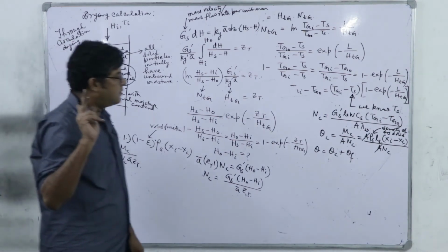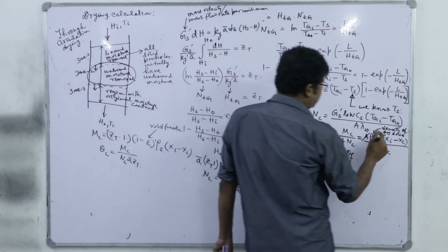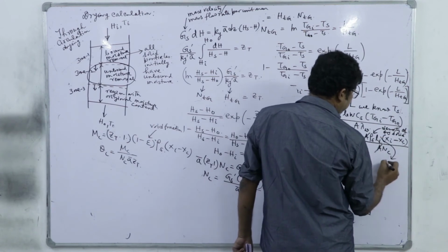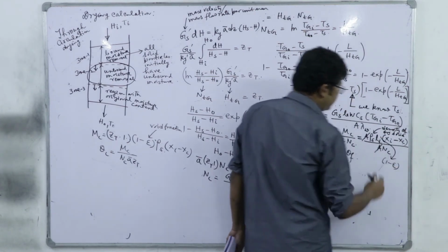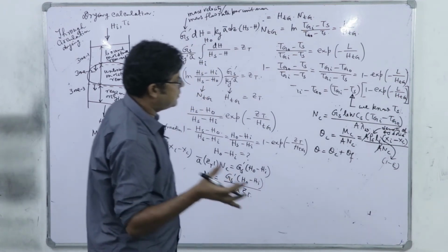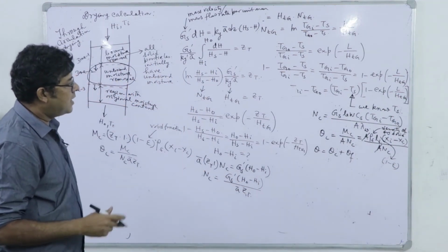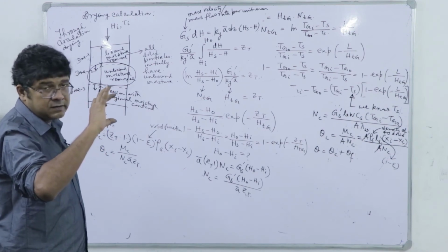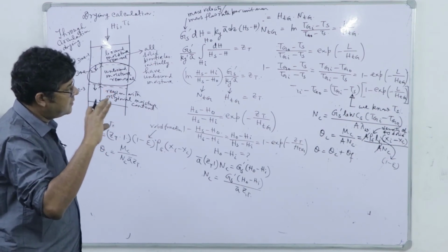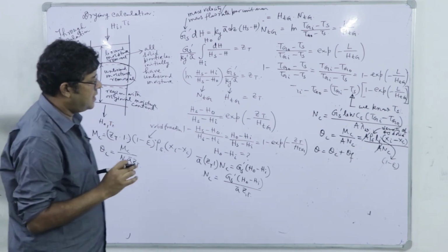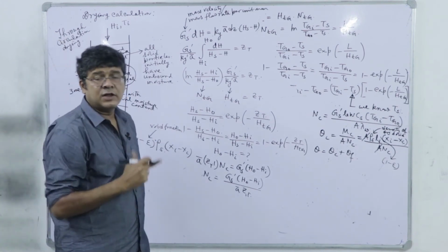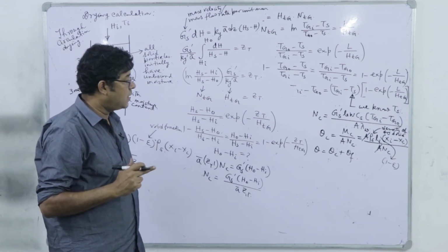So in the same sense, when we are thinking about the tray of the solid in cross circulation drying, we should multiply it by 1 minus epsilon. Otherwise, LS there is the thickness, A is the area. So A LS is the total volume, it is not the dry solid volume.